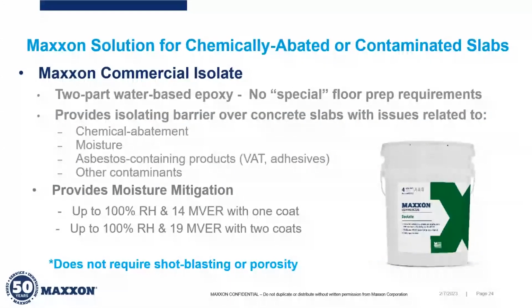So that's the first thing that it does, is it basically locks down those chemical abatement residues and asbestos adhesive residues from being able to migrate back out of the slab, which would in turn affect any of the new finishes that are put on the top. Okay, so it'll block out moisture, and again, it locks down any of these harmful contaminants from coming back out of the slab, eventually maybe compromising the integrity of what's put over the top.